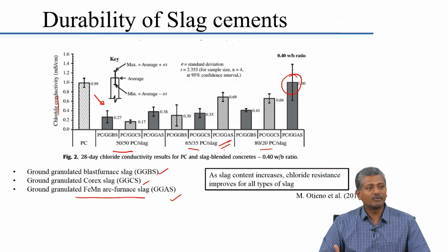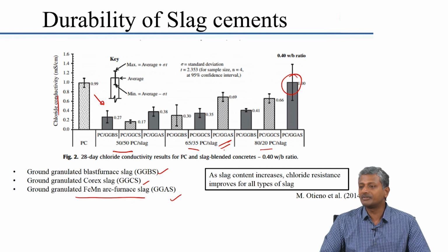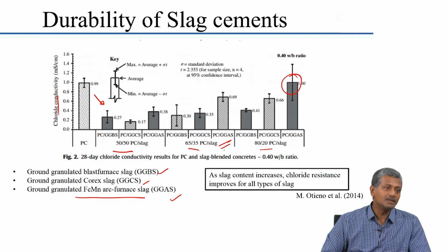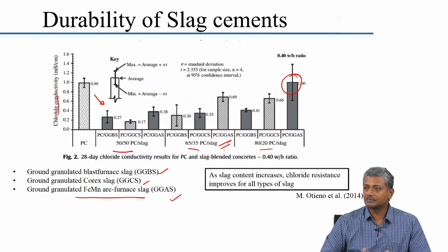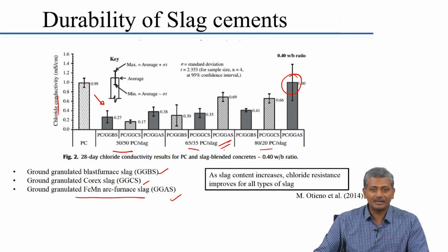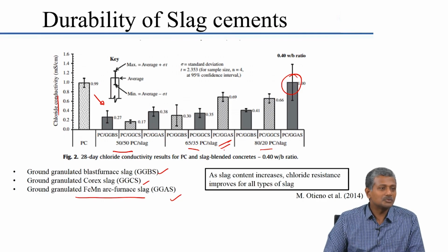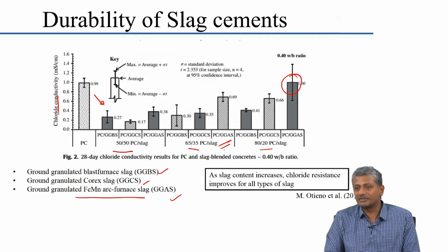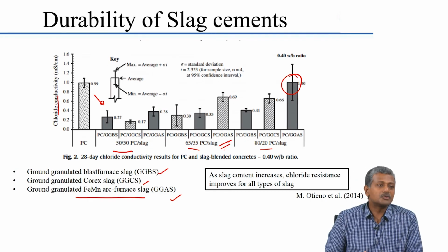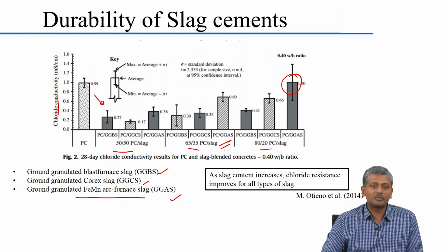Okay. And you know very well from your testing of concrete cubes that you are even allowed a 15% deviation between specimens. You can actually have a 15% deviation. It is not a good thing, but you can have a 15% deviation. So, if you have a research paper which is producing a major result conclusion at the end saying that my strengths are 15% different, it is really nothing to go to town about, right. So, you are not really showing anything new. 15% difference could be because of regular testing practice itself. So, you need to be very careful about how you investigate these claims made by people